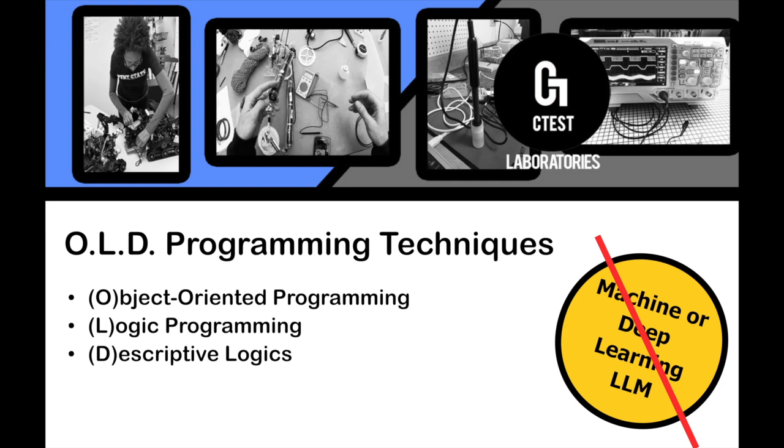But I will say that we use descriptive logics and a form of first-order clause logic to communicate between all of the microcontrollers and the Raspberry Pi in the user interface. So although we're using, let's say, TCP/IP or serial port communications or Bluetooth communications as the physical method of communicating between these components, the logical language that we're using is based off of descriptive logic or common logic, some kind of common CLIF format.